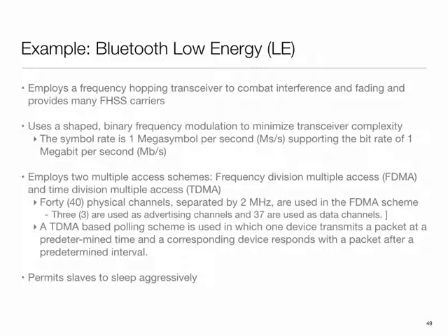BLE started in iPhone like 3 years ago or so, and now more recent Android phones have it too, and I think we're just seeing increasing penetration. Similar concept in terms of what ANT was aiming at, very low duty cycle. In particular, unlike classical Bluetooth, where for two nodes to talk, they had to synchronize, do some handshaking and all, here, none of that is needed. You wake up, transmit. You can have very low duty cycles of like 1 in 50 or things like that. So 1% to 2% duty cycle and last for years.